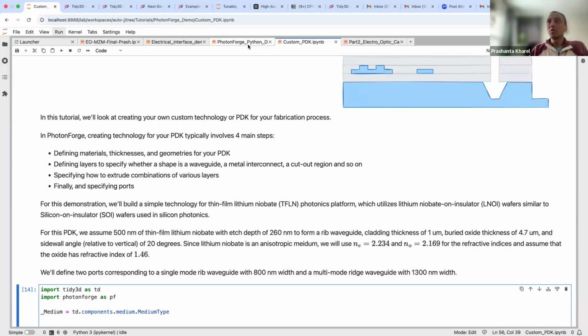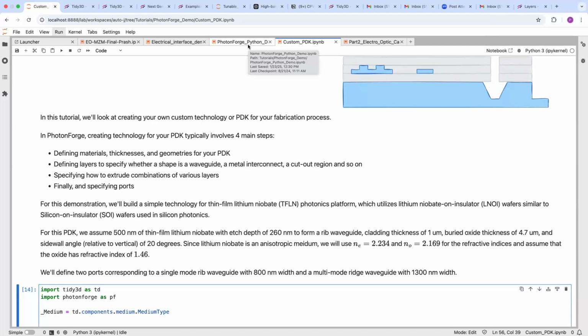That's great. Yeah, the time depends very dramatically on what model you use. If you use an FDTD model for everything, especially for very long or big components, then it will take a little bit long because you're running Tidy3D simulations. Tidy3D is already fast, like 500x faster, but if you have a 1 centimeter waveguide, you don't want to run FDTD simulations because that would take forever.